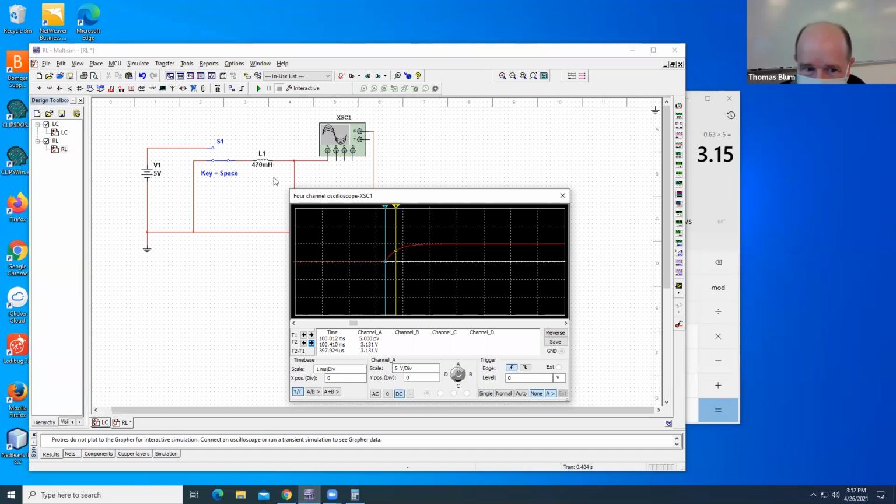I'm measuring the voltage over the resistance, and so it's the current that's changing. Before, the current sort of changed instantaneously; now that change is spread out over some time. This time constant is not the time for it to completely take place. Strictly speaking, it's an infinite number of them to completely take place. But if you do, I don't know, 3 of them, it's like 99%. What we call the time constant is 63%. Okay, it's related to the number e.